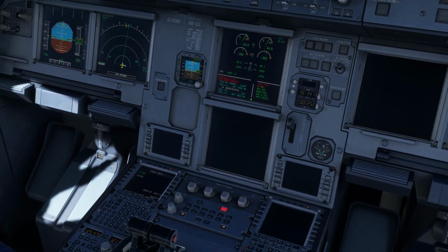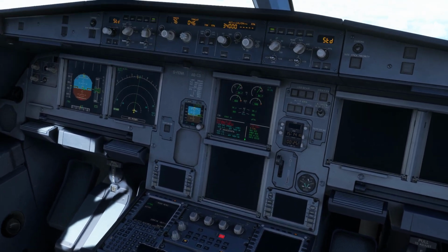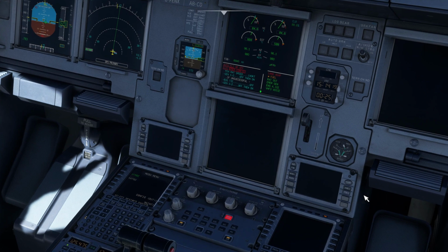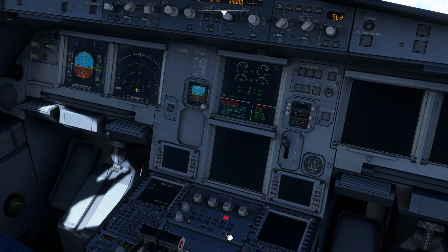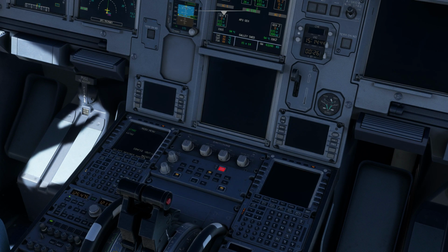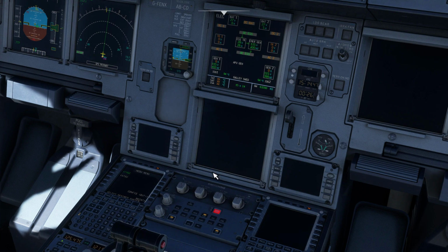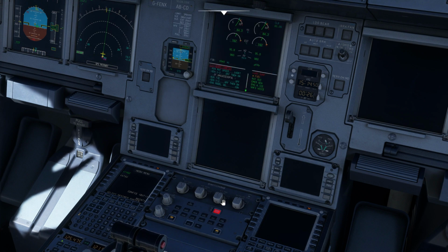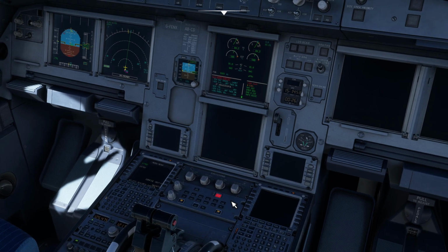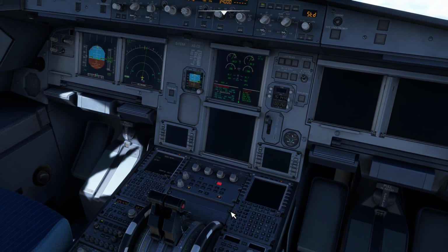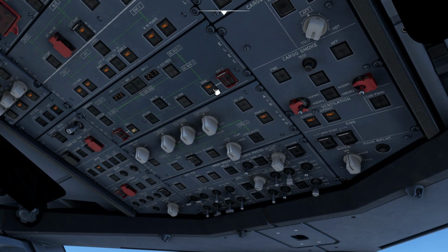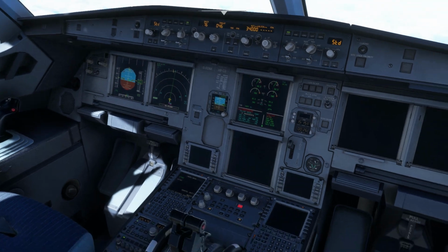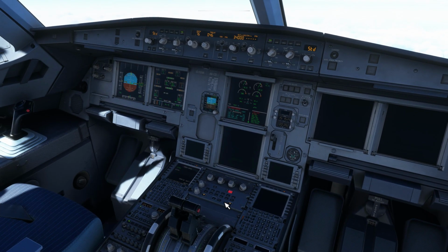We will need to divert if we cannot reset any of the systems. My radios, ECAM actions. Auto flight, autopilot off. Clear auto flight. Clear. ELEC, emergency configuration. The ELEC page also confirms this. Minimum RAT speed, 140 knots. Generator 1 and 2, off then on. If unsuccessful, well, this was unsuccessful.